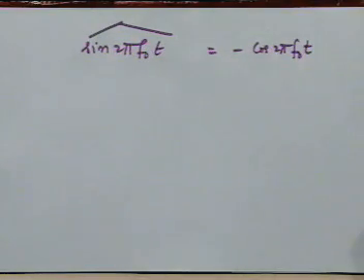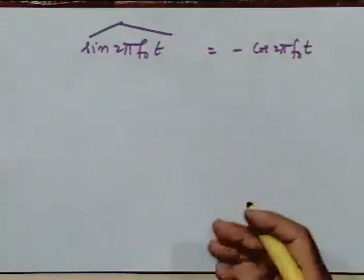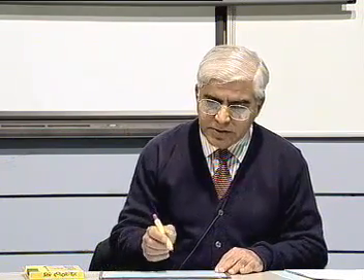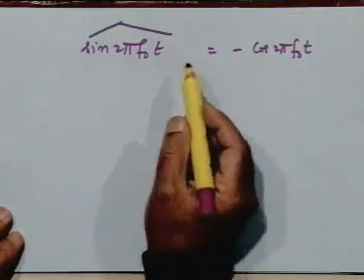Of course, these are very simple signals, so you can find it without going through the convolution operation. You will have to judge for yourself whether it is more beneficial to use the frequency domain relationship to find the answer, or to use the time domain relationship. In this case, it's much better to look at the frequency domain, because we have a single frequency component, so I know what happens to the signal. So the Hilbert transform of sine 2 pi f naught t is this.